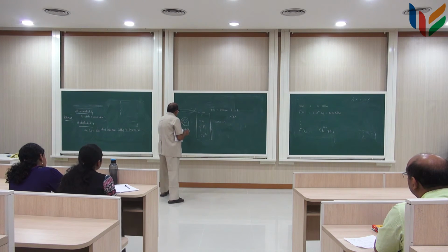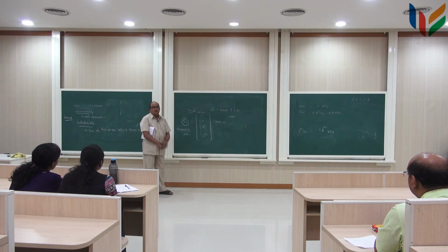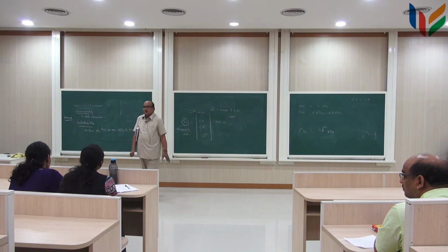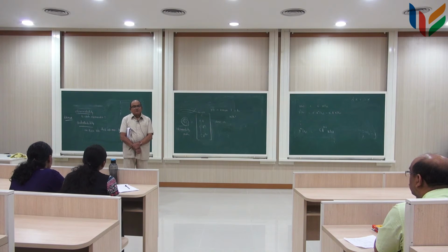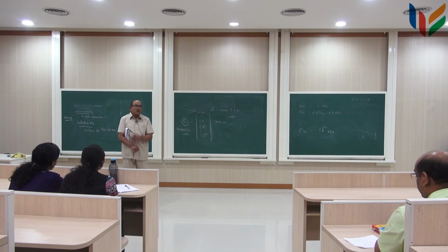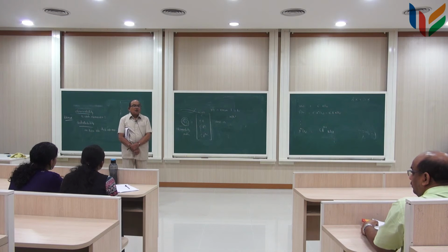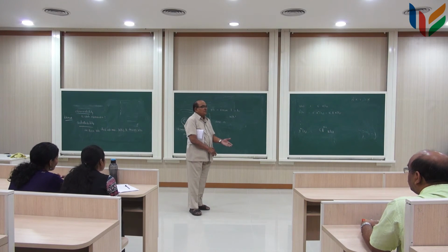Now, this matrix called the observability matrix must have a rank equal to n. If it is not so, then given y of t, you will never be able to observe x of t, and from there find out what x of t, or equivalently x of t0, is. And if you do not know the state, there is no question of controlling the state.